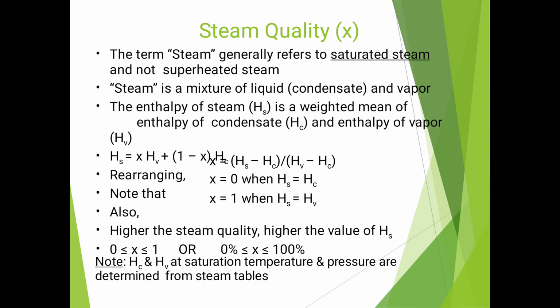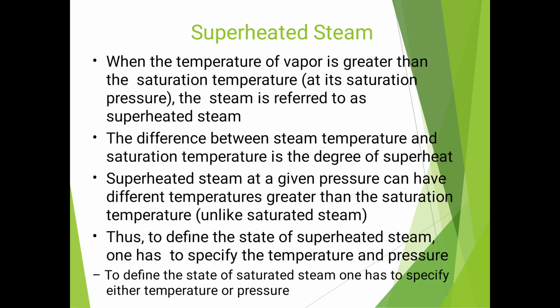Also, the higher the steam quality, the higher the value of Hs. 0 is less than or equal to x, which is less than or equal to 1, that is 0% to 100%. Here, Hc and Hv at saturation temperature and pressure are determined from steam tables.